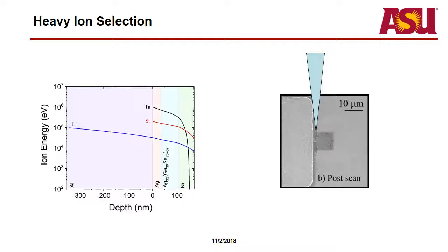So for retention of state tests, we did 2 different types of tests. One of them was a collection of different heavy ions, and then in another test we did Cobalt-60 irradiations. For the heavy ion tests, this is essentially a combined environment. The heavy ions are supplying both a total ionizing dose in addition to displacement damage once those ions begin to lose energy.